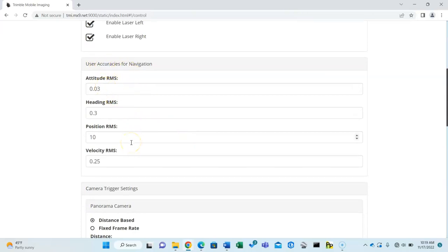This is really important based on your project requirements, right? Great to actually improve upon these values, make them a little bit tighter tolerances if you're doing engineering applications. If you are doing simply a point cloud capture for, let's say, GIS database population, and maybe your field team is doing this over tens or hundreds or thousands of miles, and it's all about efficiency and rough mapping grades, sub-meter accuracy is all that matters.